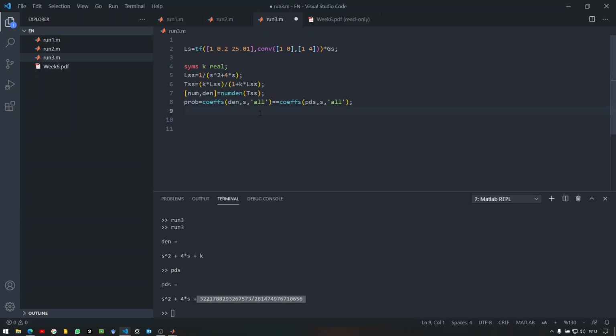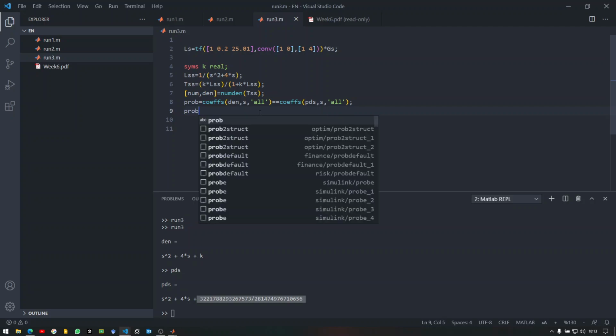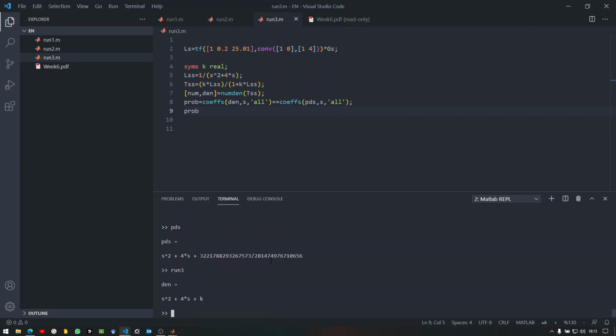This drops down the degree of the system. It reduces the degree of the closed loop because there's a cancellation inside. If that was not the case, we've seen in the tabulation method that we had to add a residue pole. Now, let's look at the problem before we solve it, but it should be the same here.